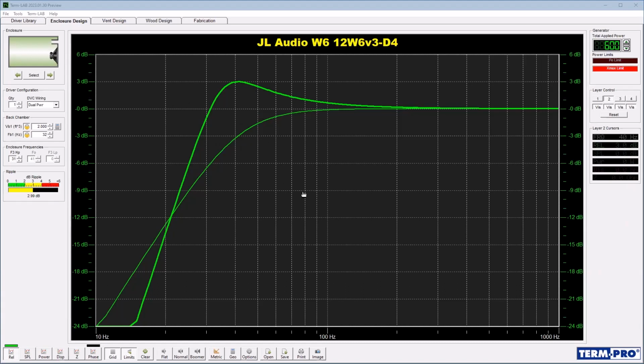So the vented box either gives you a maximum output level that's much higher, or it gives you the same output level for a lot less power. So you could use a smaller amp, or the amp doesn't work as hard. It's more reliable. There's less demand on the electrical system. So efficiency is always a big thing when you're doing these systems. You want to maximize output, maximize reliability, and you do that by focusing on efficiency.